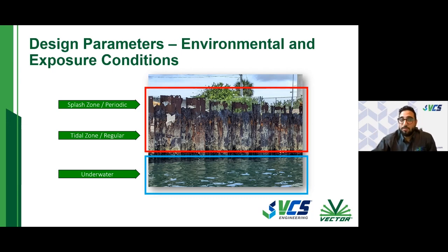So it's important to keep that in mind when you're doing a design: to design the distributed anode system appropriately so that all those regions are being protected and you're using the right type of anode at the right spacing and the right quantity.